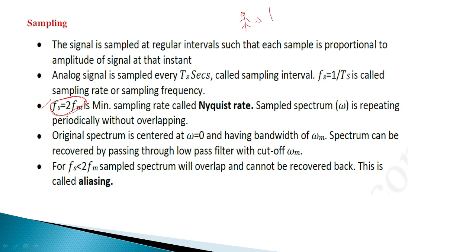The image is converted into an EM wave, an electromagnetic wave, and while sampling, the sampling frequency should be greater than 2 FM, where FM is the message signal frequency, twice the message signal. Then only, while reconstructing at the receiver, you will get the exact signal.